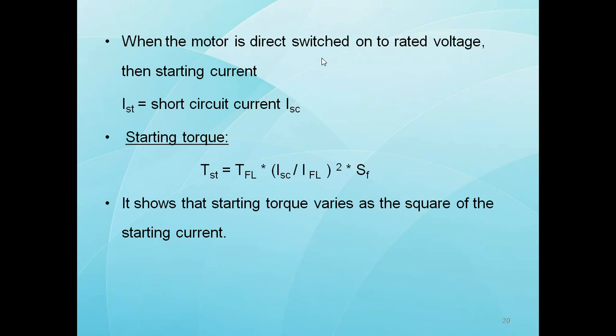So from this, what can we understand about the DOL starter? Once again I will explain the DOL starter. When full voltage is connected across the stator terminals of an induction motor, a large current is drawn by the winding. This is because at starting the induction motor behaves like a short-circuited transformer.